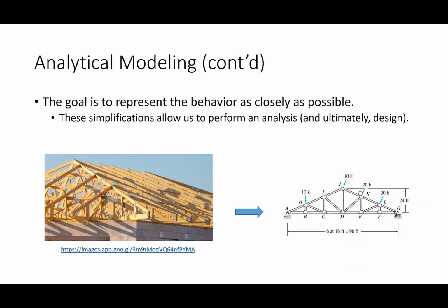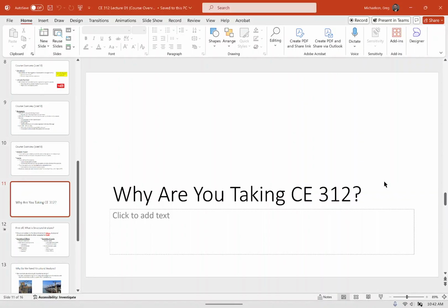I would argue that it's one of the prime challenges in structural engineering: being given a structure and deciding how you should analyze it. You look at the connection conditions and go, okay, I'm going to use a pin connection here. Or you look at another structure and go, that's not pin, that's fixed. It requires your understanding of what these models represent and how that assumed behavior applies in the real world. Again, that's kind of subtle, but it's really important, and it's probably one of the biggest challenges in structural engineering. It'll become much more important throughout the semester.